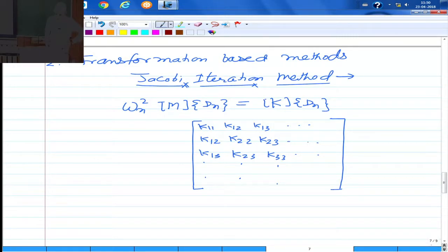Now the construction we can do is, first we take some matrix in terms of unknown parameters, and first make this K12 equal to 0, that is K12 and K21, which is the same as K12. So first we construct a transformation matrix which makes K12 equal to 0, and similarly in M it makes M12 equal to 0. Once we have multiplied by a certain matrix, we get new transformed stiffness and mass matrices. Then we try to make K13 and M13 equal to 0.